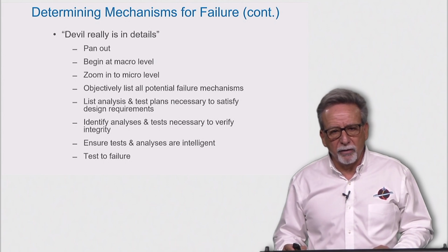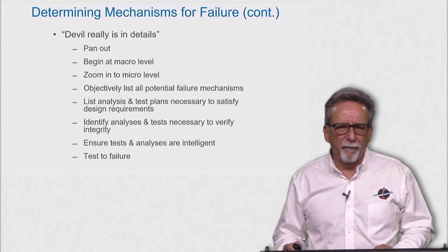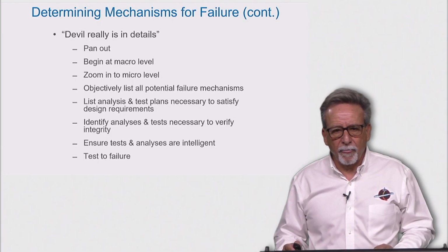What we found was the quick determination of this root cause led to the rapid development of a solution, which was to densify the lower surface of the shuttle tiles, approximately the lower 0.1 inches of the silica tiles.